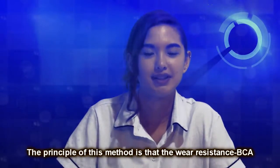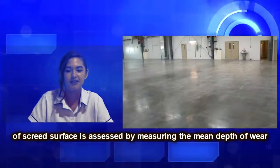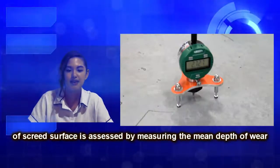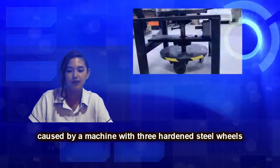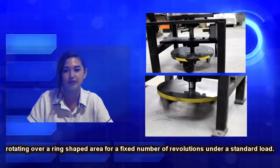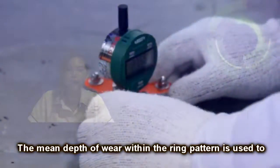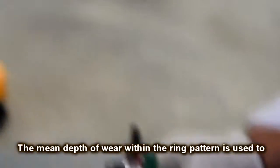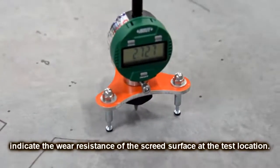The principle of this method is that the wear resistance BCA of screed surface is assessed by measuring the mean depth of wear caused by a machine with 3 hardened steel wheels rotating over a ring-shaped area for a fixed number of revolutions under a standard load. The mean depth of the wear within the ring pattern is used to indicate the wear resistance of the screed surface at the test location.